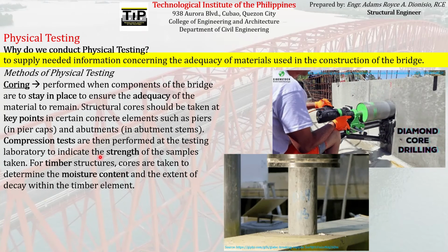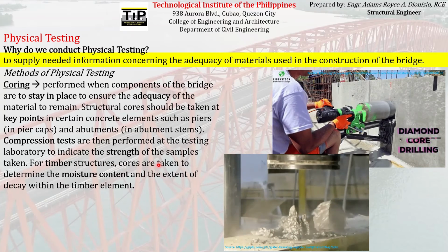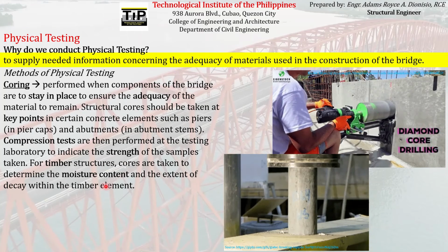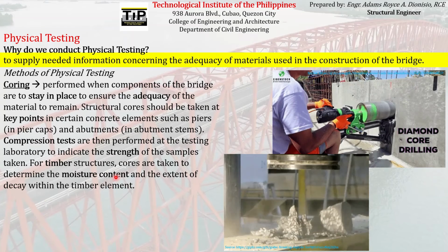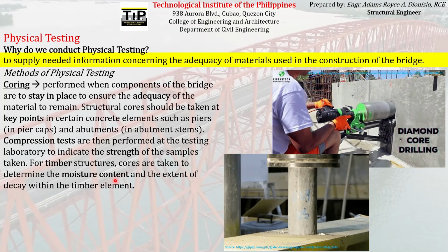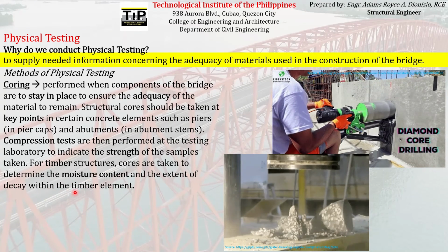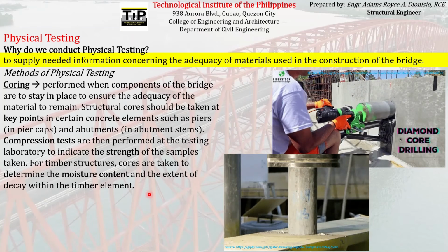For the case of timber structures, we usually conduct coring for the purpose of determining the moisture content of the timber structure as well as the extent of decay within the timber element.